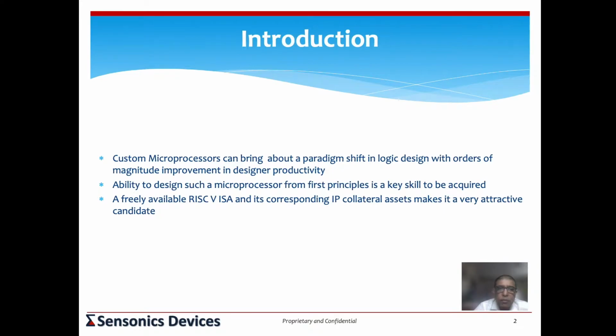A custom microprocessor can bring about a paradigm shift in logic design. It can bring about orders of magnitude improvement in designer productivity. How does that happen? It happens because you're designing a piece of hardware once, with all its timing closure and design for test and so on, all those overheads. And then you can write code in its assembly and obtain completely different pieces of logic over a period of time.